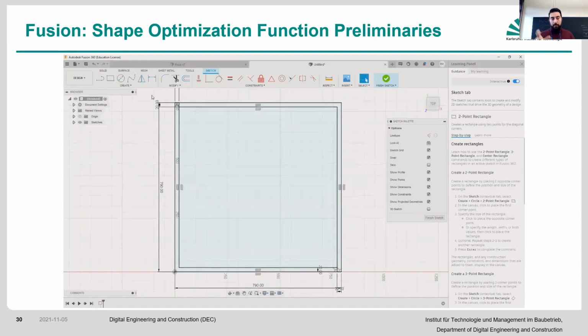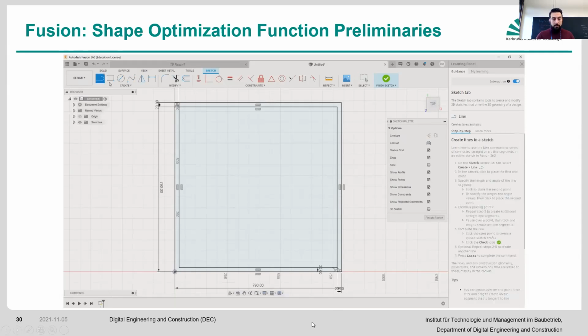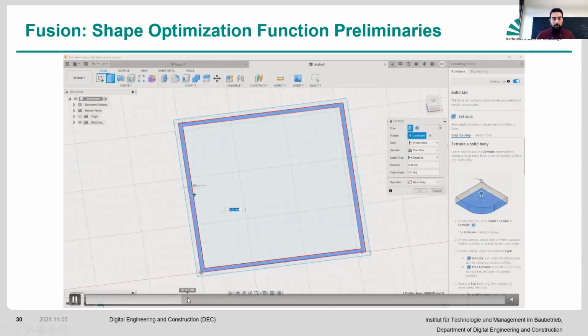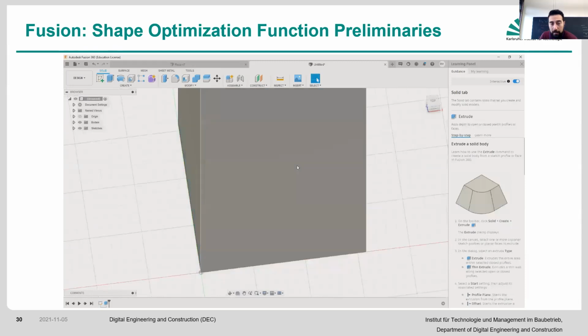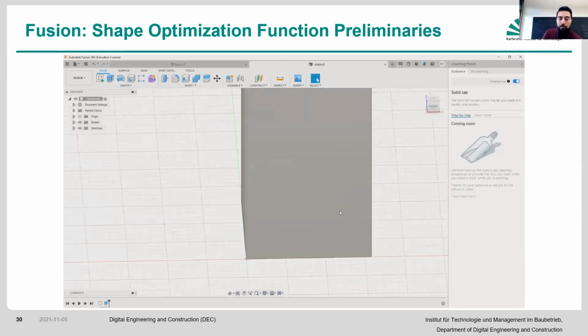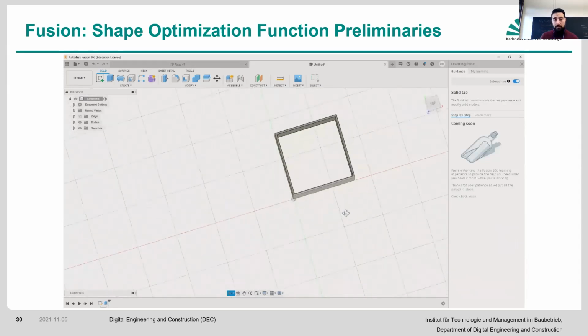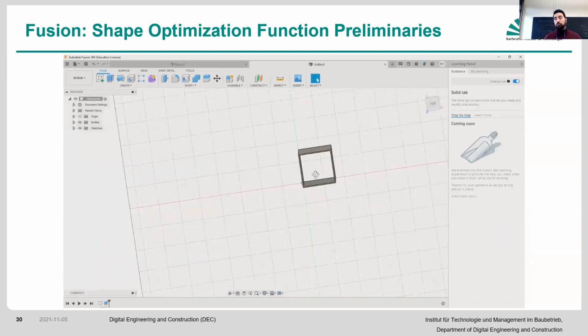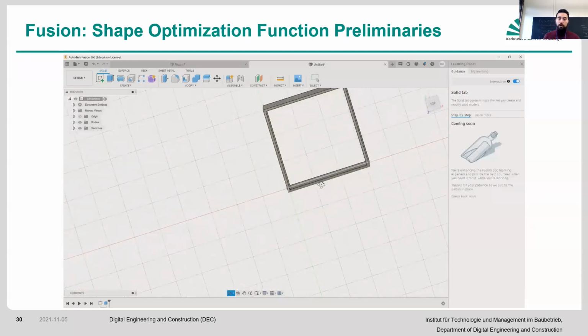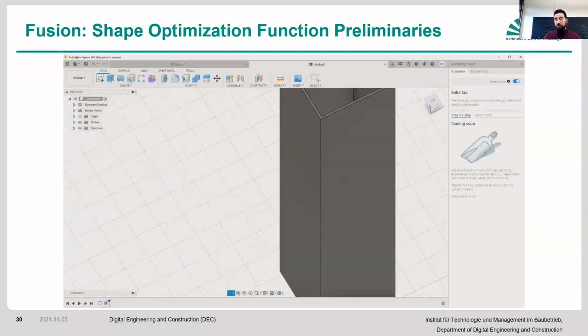You basically delete the extra parts that existed, and then you select the one that you have on the other side, and you extrude it up. In this situation, it's a 4-meter extrusion that we're requiring because the height of our column is 4 meters. So you do the 4,000 millimeters there.